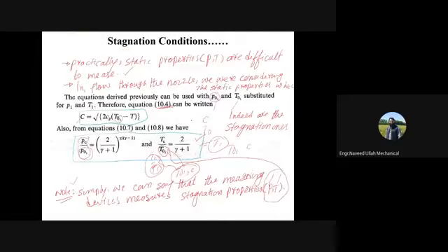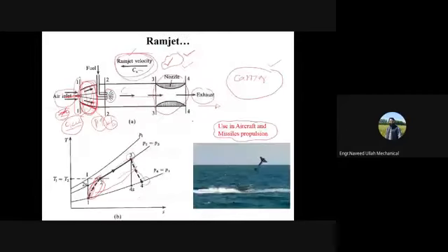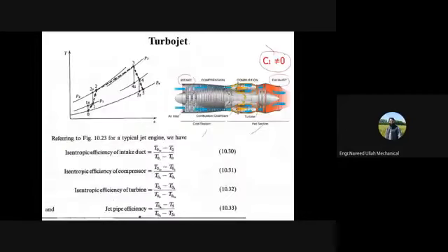तो इसलिए जो formulas हमने already develop किए हैं, आपकी book में भी इस तरह किया, बस उन formulas को आपने alter करना है, change करना है, ठीक है। So if you remember, ये मैंने यहाँ पे बताया भी था कि isentropic efficiency of the compressor is having what, (T2s minus T1) divided by (T2 minus T1), right. लेकिन फिर क्या होगा, T2s की जगह T02s, stagnation temperature, ठीक है। And same is the case for isentropic efficiency of the turbine. (T3 minus T4) by (T3 minus T4s) था, तो अब T03 होगा हमारे पास, ठीक है।